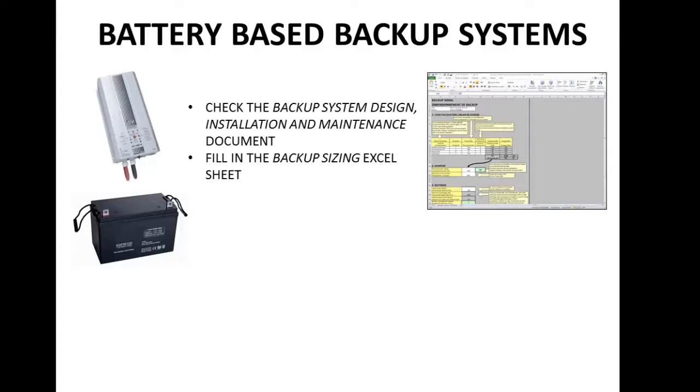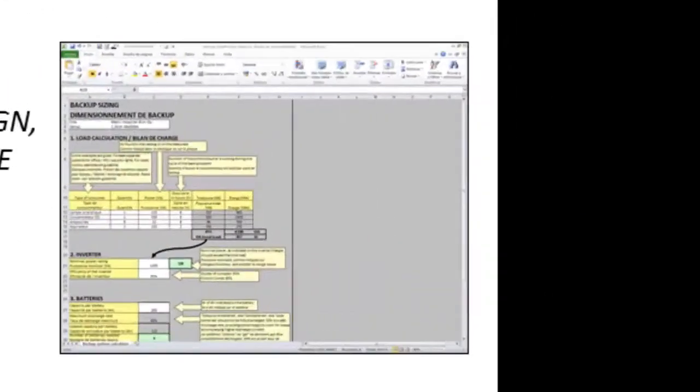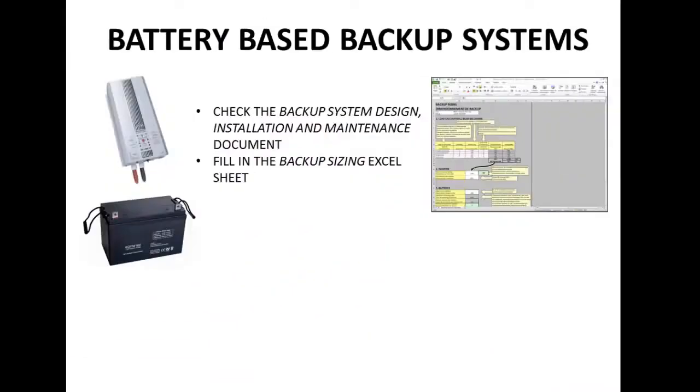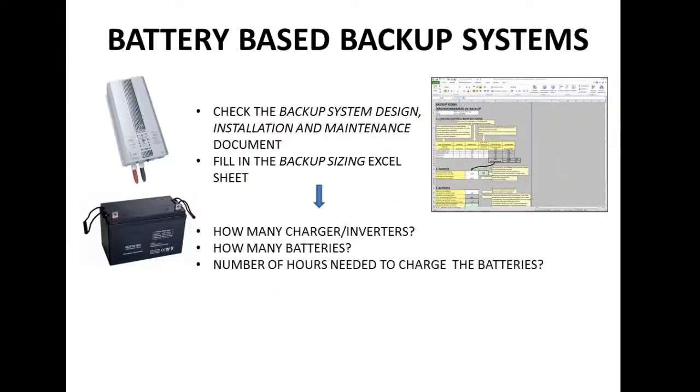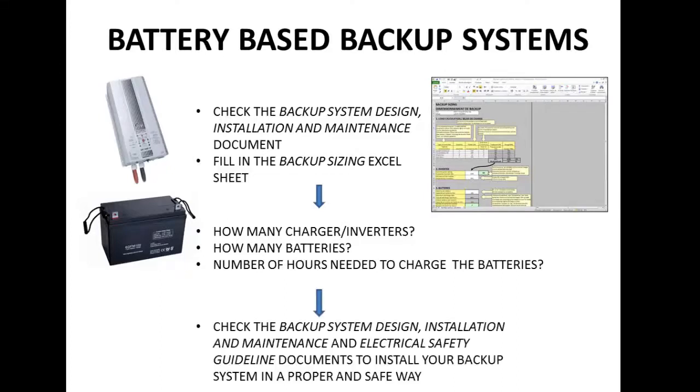In order to size correctly your backup system, check the backup system design, installation and maintenance procedure. Enter all your power needs, watts, how many hours, etc. in the backup sizing Excel sheet. With this you'll be able to know how many chargers or inverters you need, number and capacity of the batteries needed, and how many hours of electricity is needed to charge the batteries. Then check again backup system design, installation and maintenance procedure in order to have a proper and safe setup.